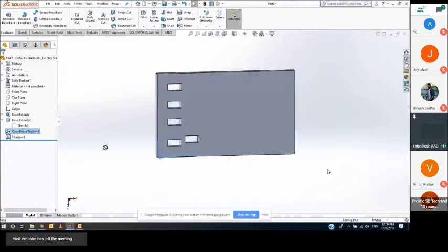So one important thing to remember is you have to create a coordinate system for a table-driven pattern. You can use a text file for inserting all the coordinates, or you can directly enter all the coordinates in the table as well.